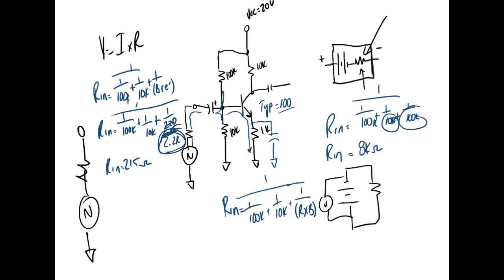When it gets time, in that power amp, to drive those speakers, we are not going to use a common emitter because of this high output resistance, or high output impedance. But we can use this guy to get ready to give us the drive. Does that make sense? Usually we get a lot of gain out of it. If it's designed correctly, out of a common emitter you get both voltage gain and current gain, which means we can get quite a bit of power gain out of this thing, right?